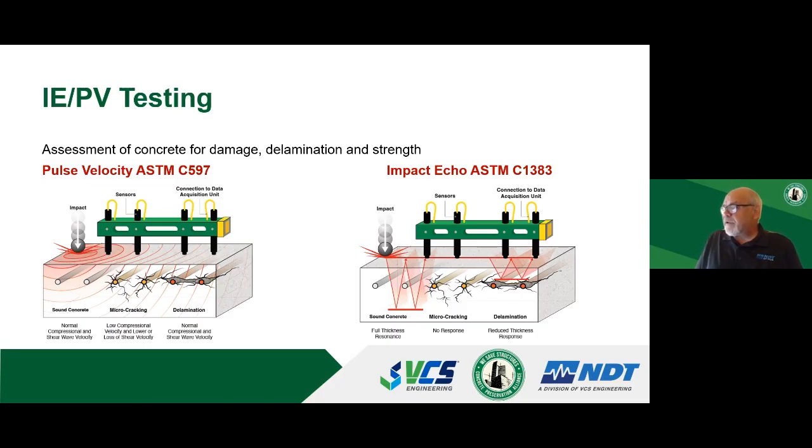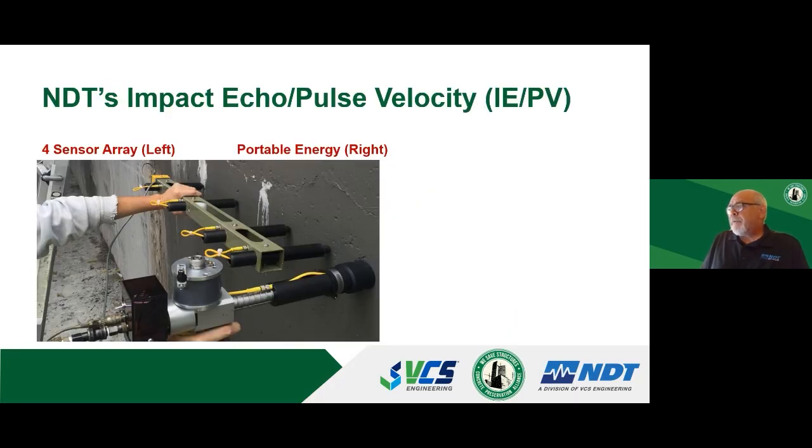On the right-hand side of that screen, that frequency without any delaminations would oscillate maybe at a 9.5-inch thick frequency. So the deck is 9.5 inches thick. And it's 9.5, 9.5, and all of a sudden it changes to 3.5. And in this certain area, that thickness frequency is 3.5 or 4 inches. Well, if the rebar cover is 3.5 or 4 inches, that's a conclusive way to determine that in this area there is corrosion and there is debonding and delamination of the existing rebar within the concrete.